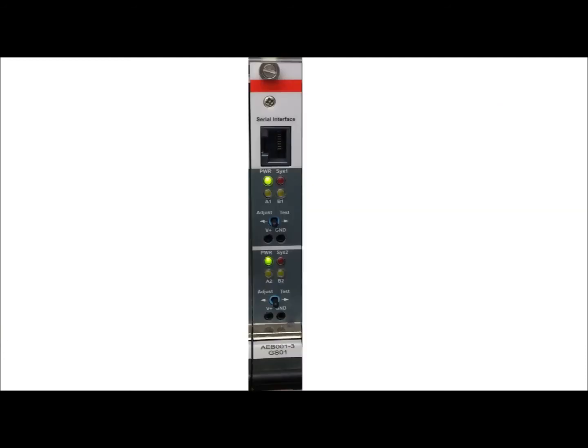The AEB receives analog information from the wheel sensor via the BSI and converts this into a digital wheel count. This is passed on to other AEBs if required. The AEB receives digital wheel count data via the CAN bus from other AEBs.